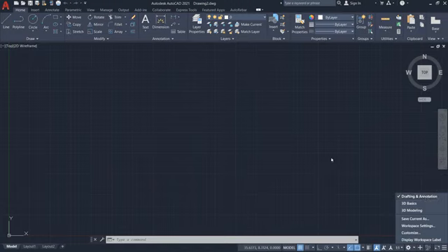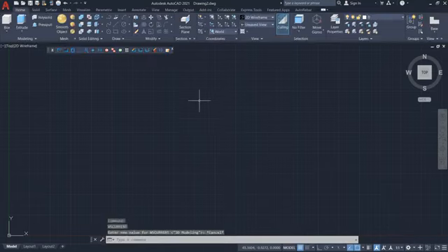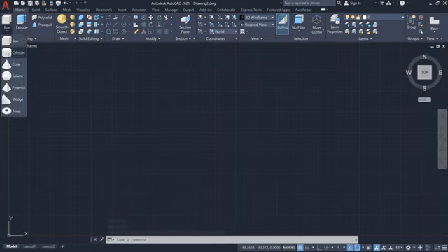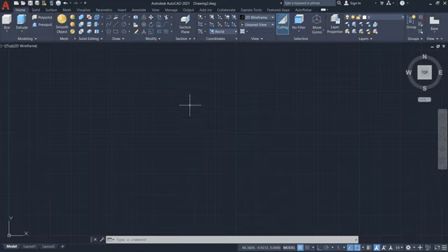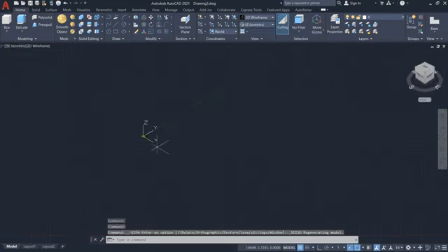To draw the 3D modeling, we have to select 3D modeling, then the tabs of 3D will appear. Here, box, cylinder, cone, we directly draw the 3D objects. In this drawing I will show from the basics as a beginner level. First of all, here in the view options, you can set any view like southeast view, top view, bottom view. So in this drawing I will select southeast. You can select as per your requirement. Okay, that is a 3D view.